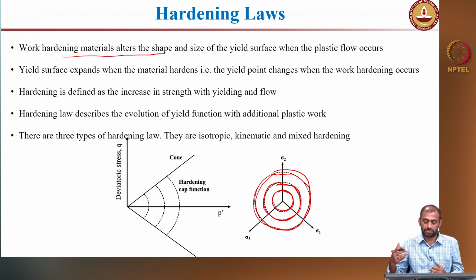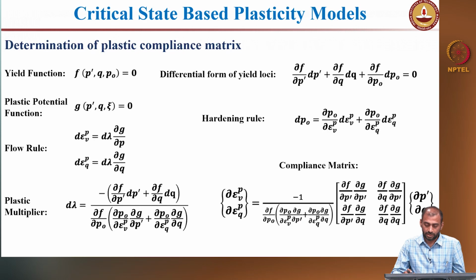So, when there is some shearing because of seismic events or earthquakes, that particular short term shearing sometimes translates the yield locus, so that you can observe a kinematic hardening. Of course, there is also mixed hardening, where the failure locus expands as well as translates. You see all these different types of hardening under certain conditions.